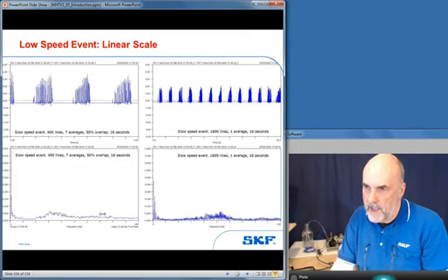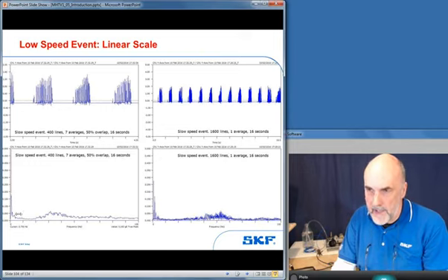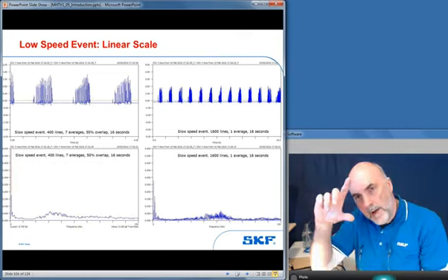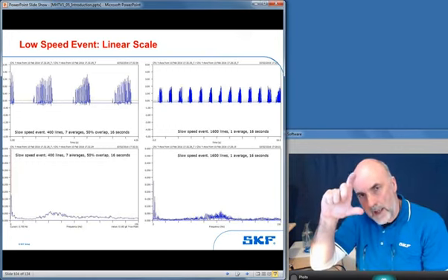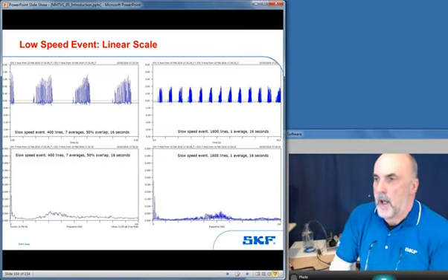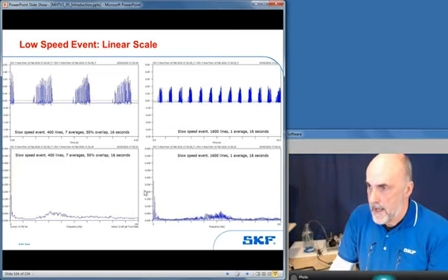So if you're really interested in getting a representative statistical measurement of where the level of the carpet is versus the peak, then averaging, as I previously explained, is possibly the way to go, because the random part of the signal will average to its mean, leaving you with the periodic.